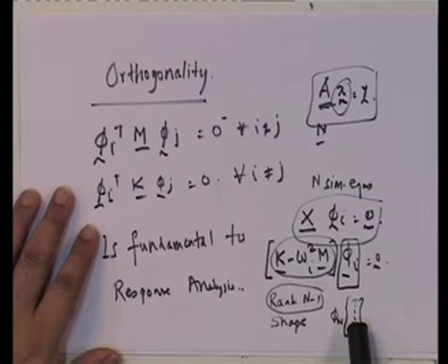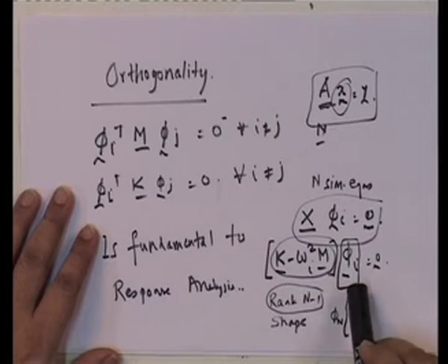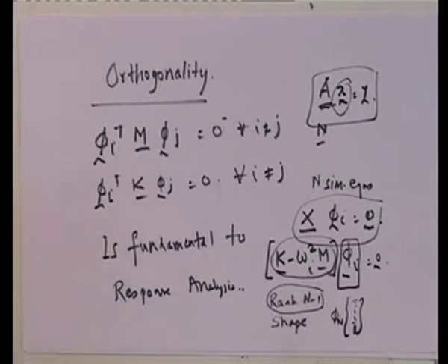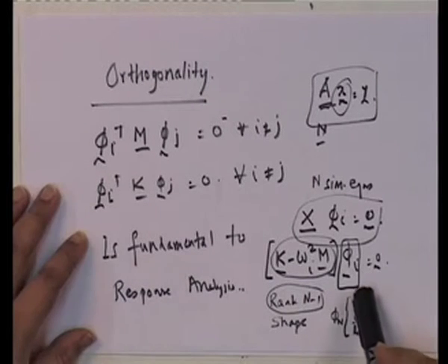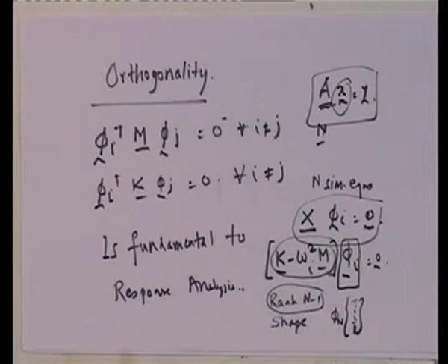That means essentially you do not know one and you are getting all of them in terms of the other. Okay. Now, this brings in a certain amount of randomness in the mode shape. Okay. And why is that? Because well, you may choose phi n to be 1, I will choose phi 1 to be 1, it will be the same shape, but it will look like a completely different mode shape.